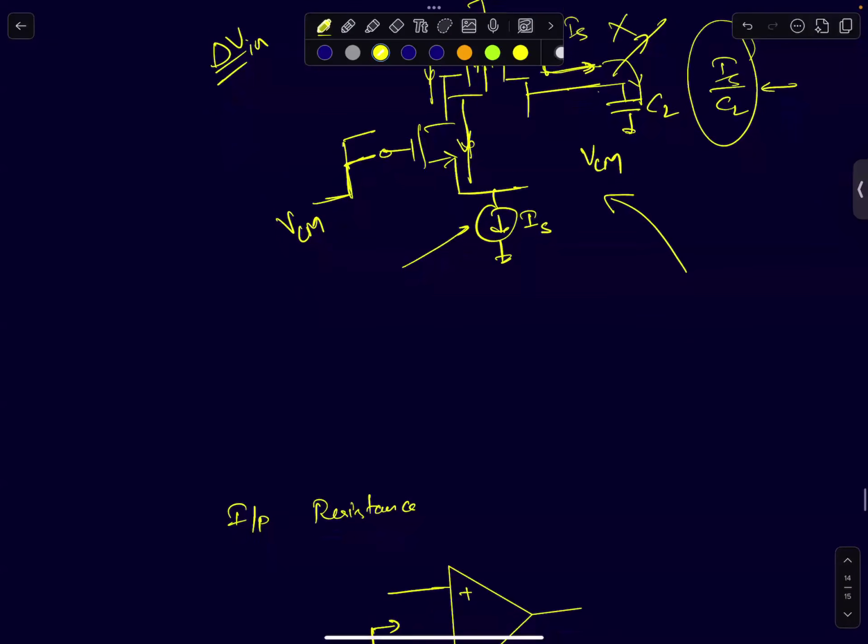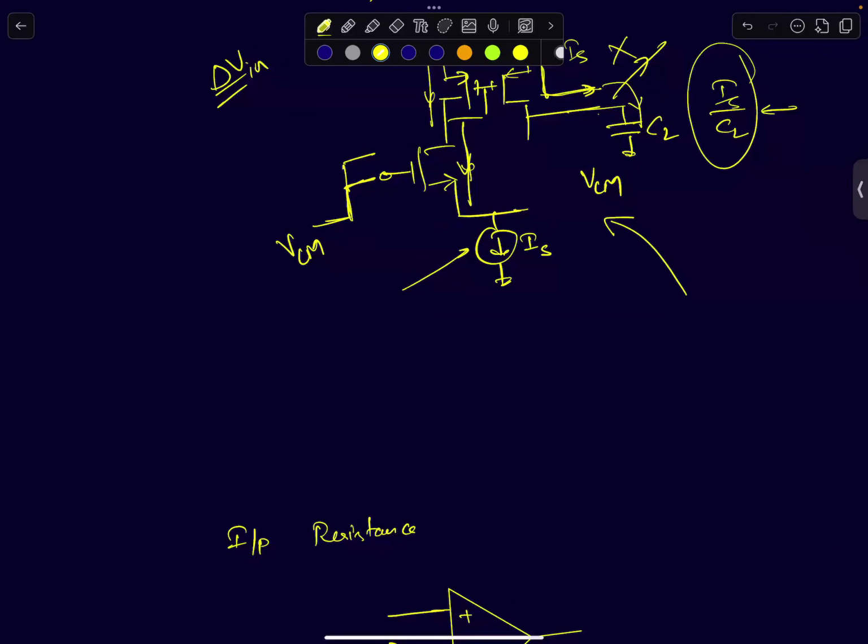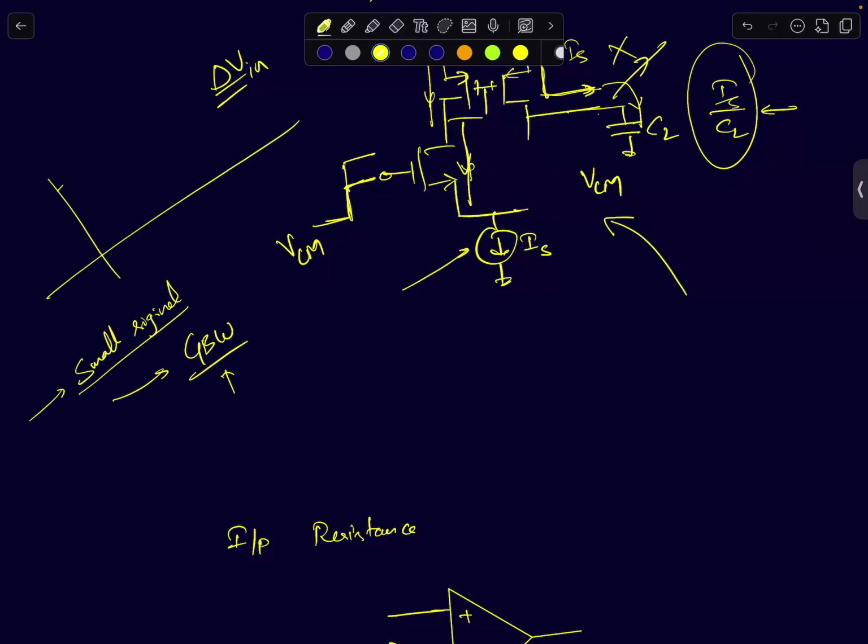It's a large signal parameter. Gain bandwidth product is a small signal parameter, right? We used a linear LTI model for the op-amp, using small signal models, and that's how we got this. We derived this from a Bode plot. A Bode plot is a small signal response, right? It's an AC response of the amplifier. So it's a small signal model, and you get the gain bandwidth product.